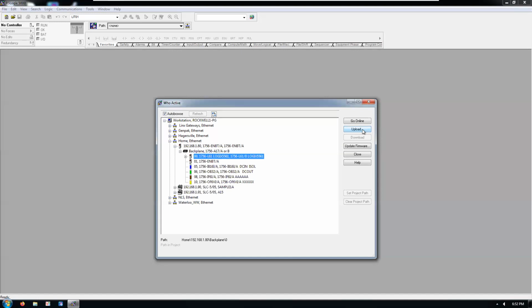The big issues end up being your programming software A will take control of your network card, and then programming software B can't communicate with anything. And unless you know how to disable the other software, you'll never be able to get online with your stuff. So there's a pro tip: if you don't want to carry 8 laptops around, virtualize your programming environments.